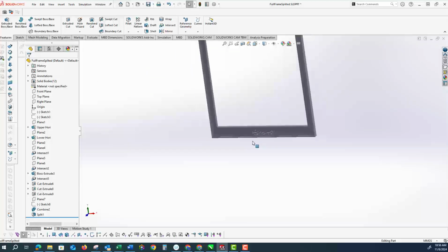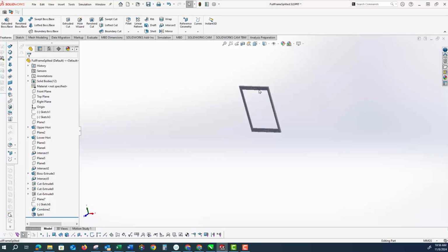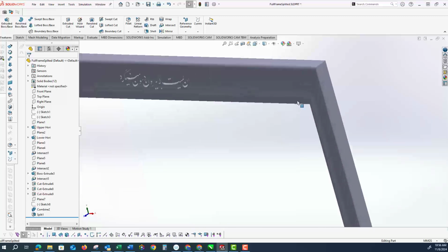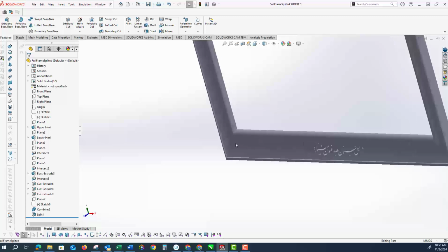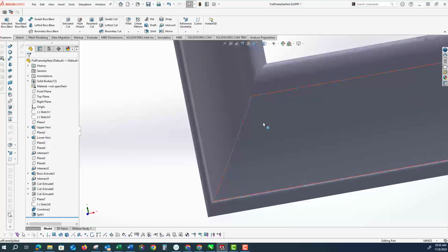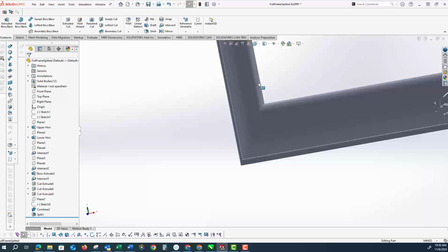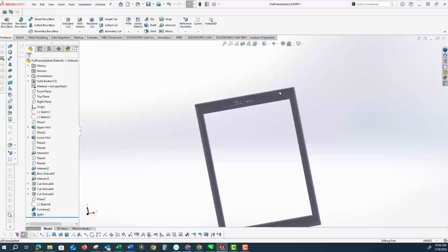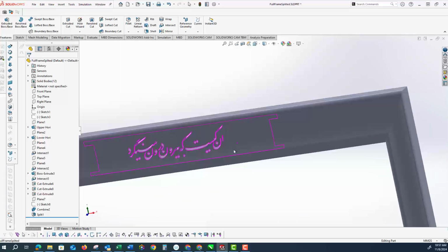I would skip the process of making a profile and having this profile swept around the line, or any other technique to make sure these interfaces match, because this frame is made of two different thicknesses, and that's not a 45-degree interface. Once this is ready, the next step: you see that these are being imported as sketches.